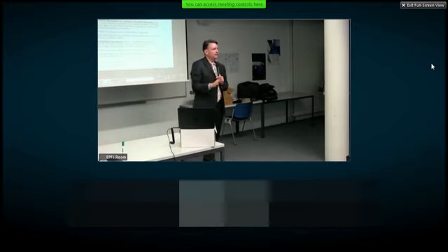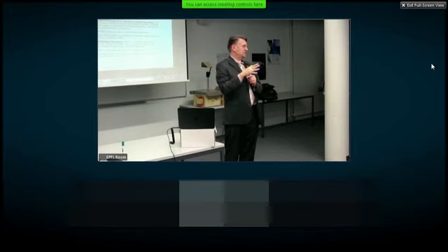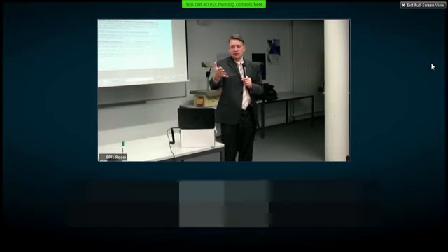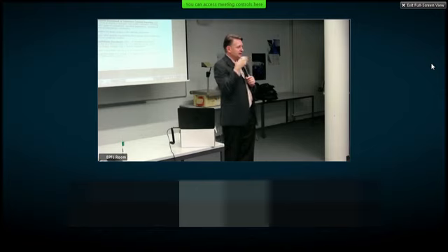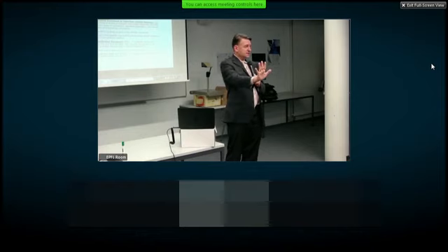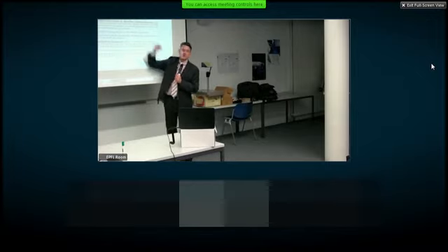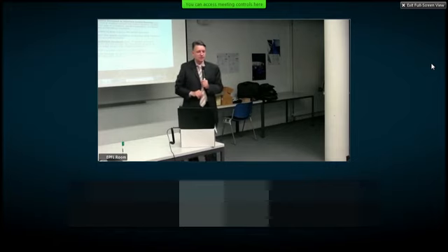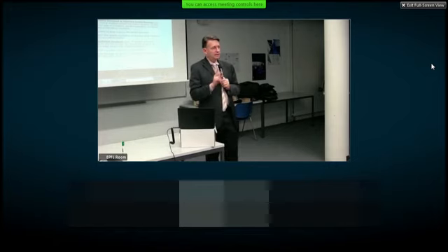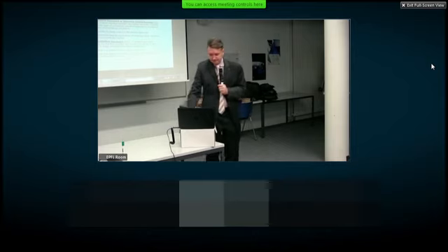So for example, let's say your company makes a very fancy camera or sensor to be used on a spacecraft. But you don't know who's going to use that camera, how they're going to use it. So what you're defining is essentially your side of the interface, physical, functional, and then it's up to whoever your customer is to take the IDD and turn it into an ICD. But the IDD is only one-sided, unilateral, and the ICD is bilateral interface definition. Does that make sense? Okay.